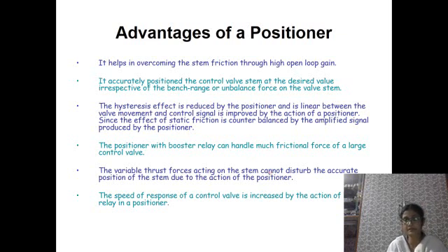Hysteresis effect is reduced by the positioner, and linearity between the valve stem and the control signal is improved by the action of the positioner, since the effect of static friction is counterbalanced by the amplified signal produced by the positioner. A positioner with booster relay can handle much frictional force, since the signal can be enhanced using the booster relay.